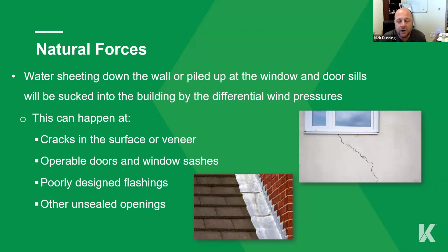And I always remind people too, they are hurricane impact windows. They're not fully water resistant beyond the weeps. Even a really well installed one in a hurricane, you're probably going to get a little bit of water in them. That's not the end of the world. It's greatly reduced, but keep that in mind as well, that there's not a bulletproof window system that doesn't let anything in out there. And like you said, we don't want that for a building at the end of the day anyway. No, it would cause a lot of issues.